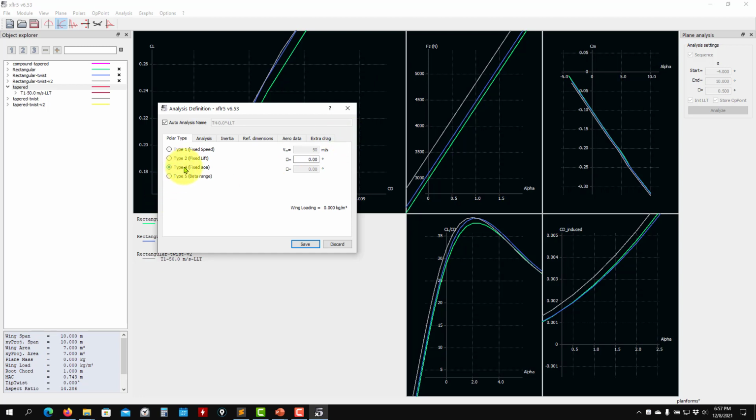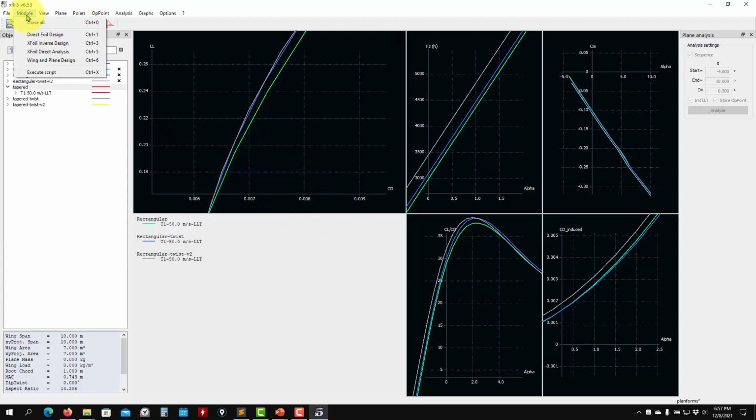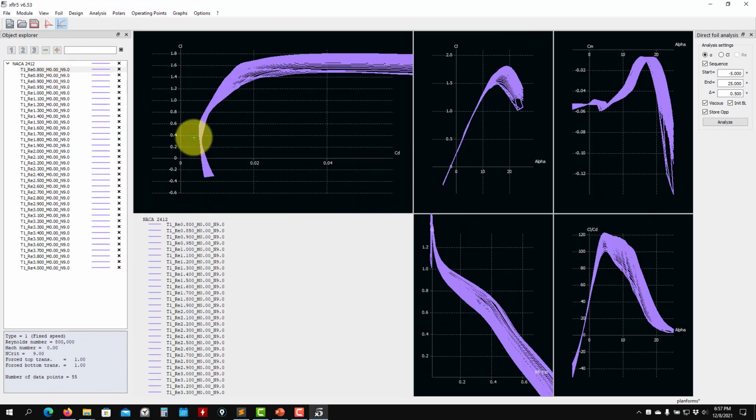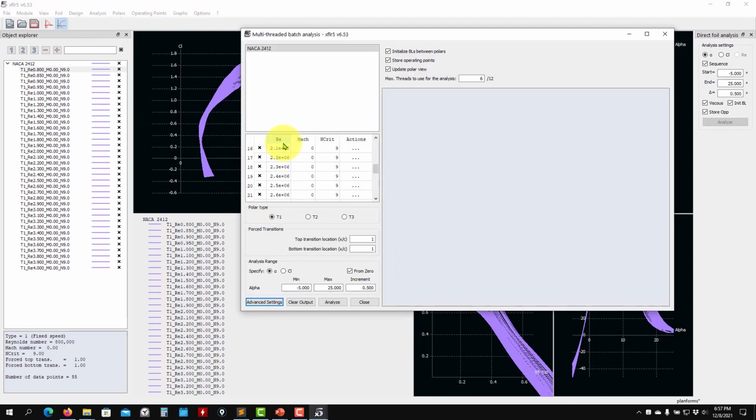For instance, you fix the angle of attack, and then here you will change velocity. So we'll show you that, and you can construct everything as a function. Now it's velocity. Now velocity is constant. See that it's telling you that you have all these Reynolds numbers. So you have to be sure when you generate your wing that you cover everything. See that I have already my Reynolds, so that you can do a batch analysis here, and you need to construct this table.